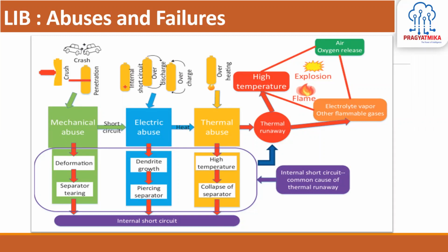So we need a mechanism to avoid this thermal runaway. Many people are using the BMS. BMS is just a protection device. It is not going to give you safety against many of the hazards of your battery pack. It gives you safety up to an extent for the known electrical regions. It will not allow the battery pack to go into overcharging or over discharging. These things it will not allow.